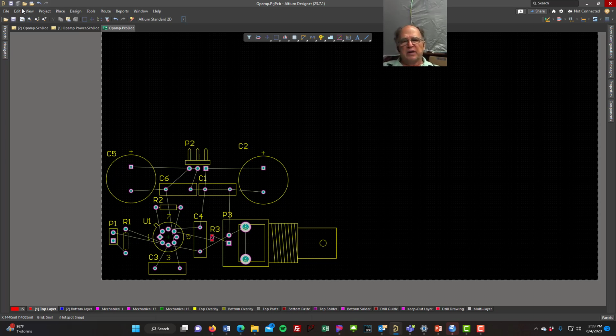I'm a little worried about this footprint though. Look at that thing. Did you ever get an op amp in one of your kits that looks like that? No. Well, they do still make that part. It's usually a military spec part. They call it mil spec. It has higher tolerances. It can operate in colder temperatures, hotter temperatures. It's more resistant to higher and lower voltages, higher precision and all that, but we're not using that in our project. And when I look at this, I'm like, man, that's the wrong footprint.